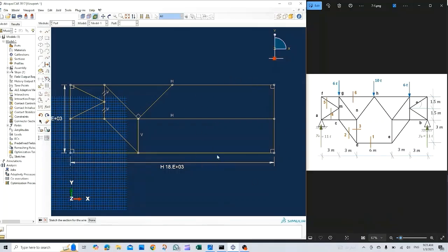Here the right part is really a mirror to the left part. So let's have the line of the mirror. Click line, click on the point H, and we must have this a truly vertical line, or let's have it using coordinates. Better 9,000 in the X direction and say 0 in the Y direction. Press escape.